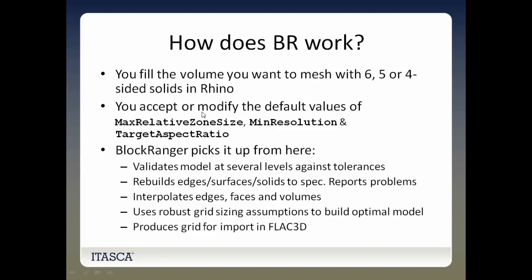BlockRanger picks it up from there. Basically what it does is that it takes the solid, validates the model at several levels against tolerances, rebuilds edges, surfaces, and solids to spec, and reports problems. It's intelligently designed so that when it's completed, it signals which blocks have problems. It leaves those blocks on the screen as highlighted elements, so you can hide the rest. At that point, you can look at the blocks and explode them. If they're 6, 5, or 4 sided, they should be good. If they are 8-sided, you should explode them and see why they're 8-sided.